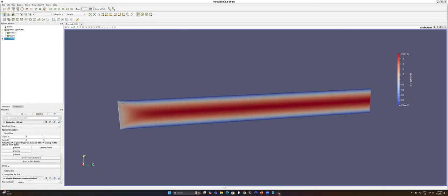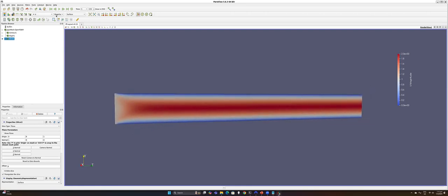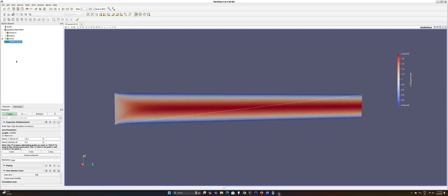Anyway, so this is one of the things you could basically say, hey, let's define the plot over some particular line. So you can see that there is a line going from this side to this side, right? Do you see it? So we need to define 2 points. If you truly want to see the values across this cross section, then we can define those 2 points, right? Let's start from the x. Let's say negative 0.2, for instance.